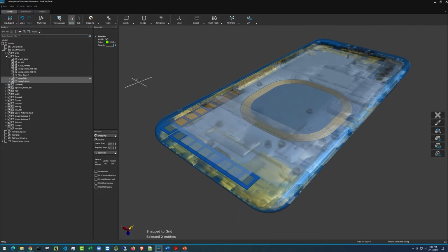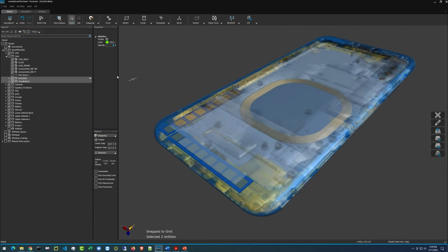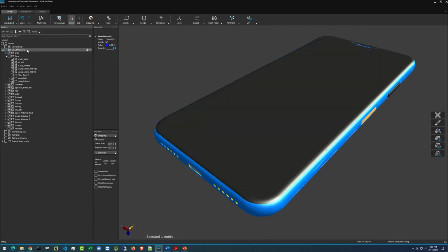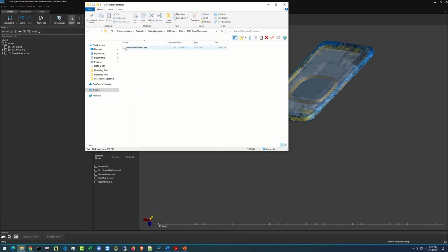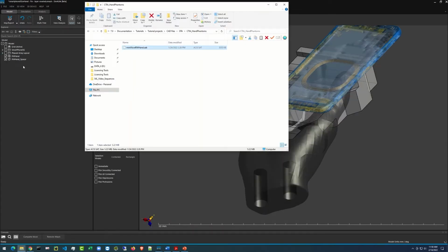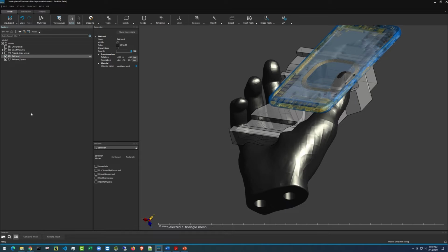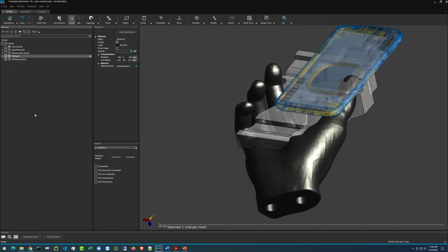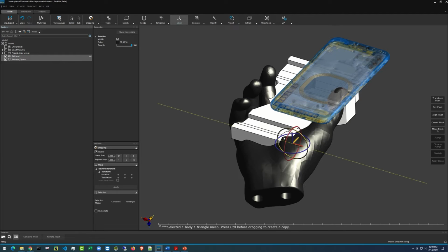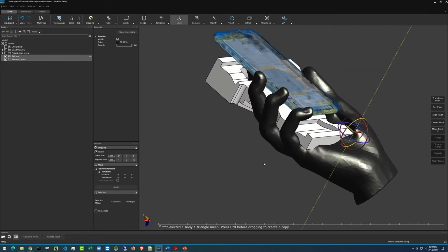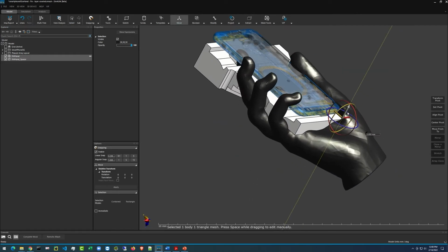And as an example, we want to determine the over-the-air parameters when we hold it in our hands. First, the user drags and drops CTIA's millimeter wave hand, in this case the right wide hand, which already contains the appropriate model parameters valid from 3 GHz to 110 GHz. Next, the user positions the phone in this hand according to CTIA requirements.